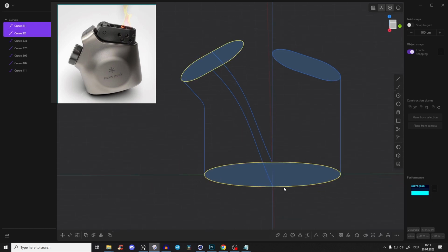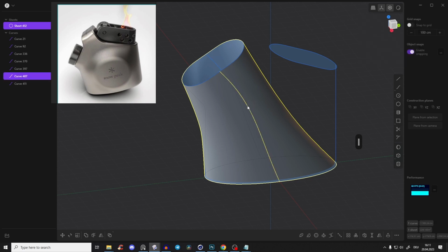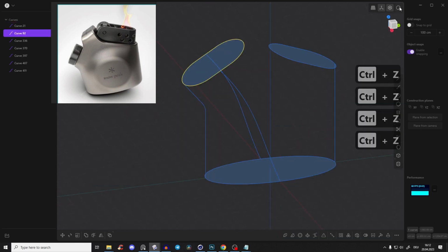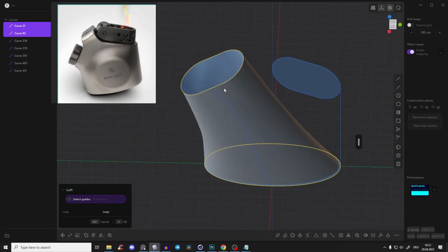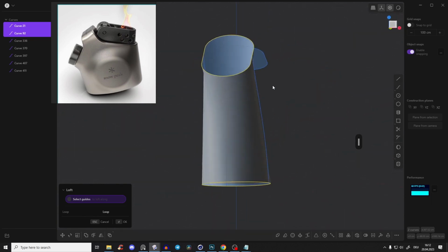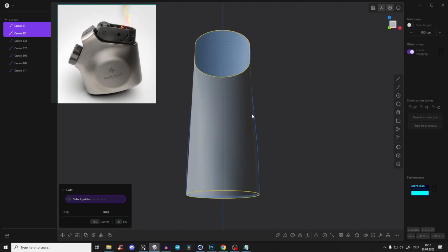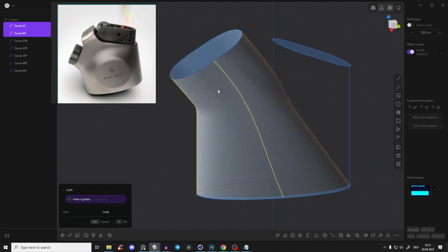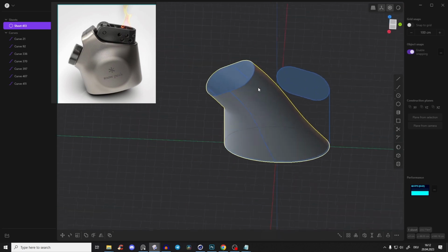And now I want just to check if everything looks fine. So I will select this curve and this curve, press L. Let me go out of this view here and Shift and Shift. So again, let me select this here. So this curve is selected and this here and press L for loft. And now we want to adjust it to those cages here because you see it's not adjusted to that curve. So press Shift and just click this one. Also the same for this and also the same for this, right? So yeah, that looks fine.